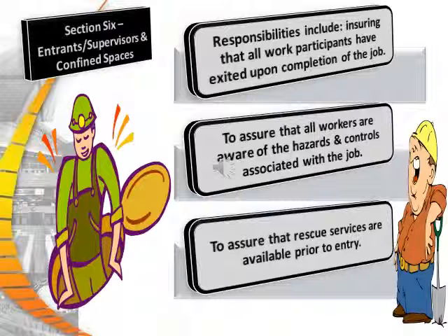Responsibilities include ensuring that all work participants have exited upon completion of the job, assuring that all the workers are aware of the hazards and controls associated with the job, and assuring that rescue services are available prior to the entry.